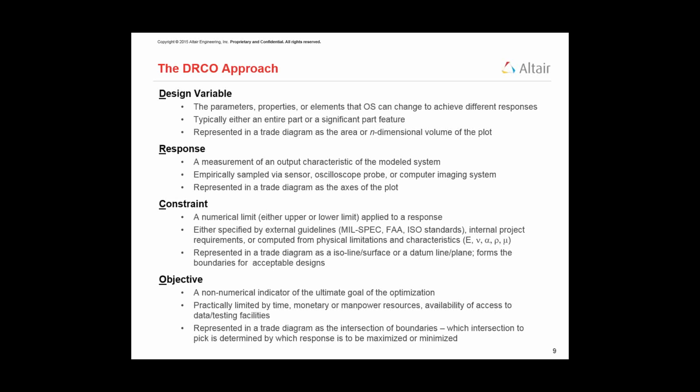And the constraints just basically create a bound for our optimization, allow us to limit it to reasonable or acceptable values. And then the last response, the only one that wasn't constrained, as we said, is an objective. Typically to minimize something, minimize stress, minimize compliance, minimize volume, minimize mass. And that's how we set up for optimization.